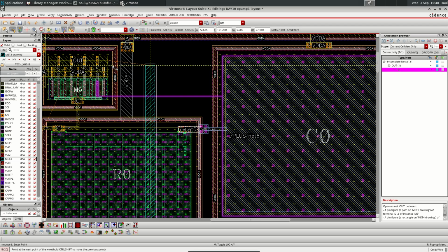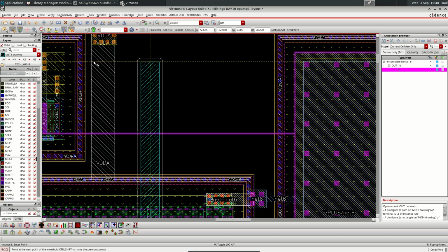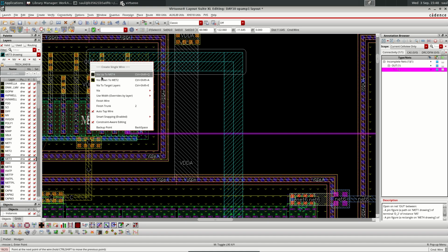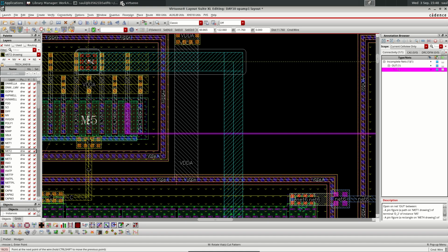And here I will come like this. Let's see if down to metal. Oh, that's okay. If I am not happy with the amount of contacts that were automatically selected, I can do it manually, but in this case the output is just 15 microamps, so it shouldn't be any problem with 9 contacts. I can do it manually with more if I want.